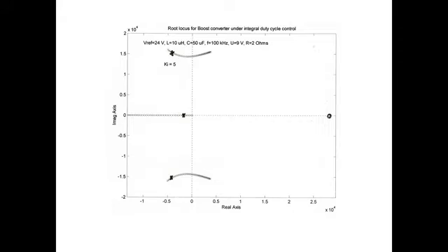Here we go. So the open loop pole locations are the ends here. And this is for a load resistance of 2 ohms. This is one end of my load range, the heavy load end of my load range. We can see that for Ki, because I have this integral gain of 5, I'm going to have a pole here that's due to the compensator, and the poles that are due to the plant are going to be here. And the right half plane zeroes out here. Okay? So that system ought to at least be stable.